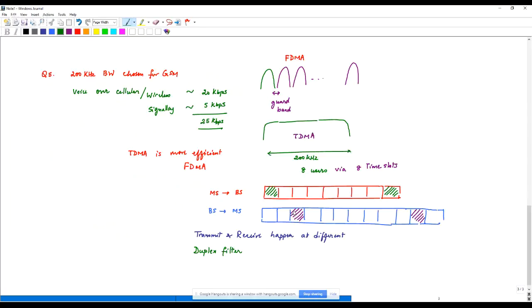The other thing, which is, I think, a bigger advantage from the design of a communication system, notice that there is a lot of idle time when the mobile is not doing anything. It's not transmitting, it's not receiving, it is idle. So typically there are 6 time slots when the mobile is idle. Now what can the mobile do during this period? The mobile goes and measures the strength of neighboring base stations. Why would you do that?